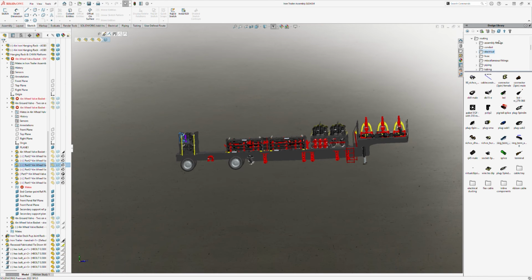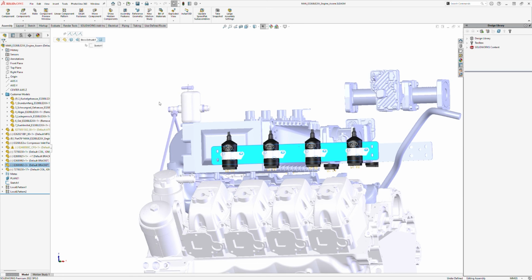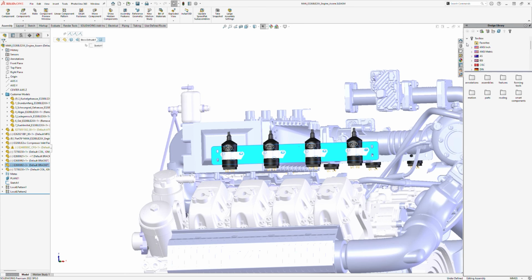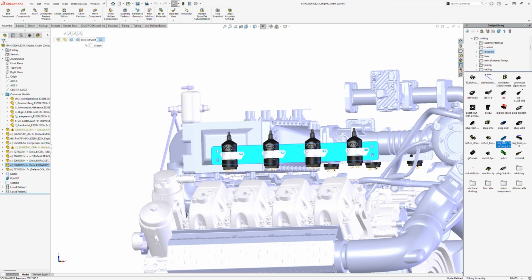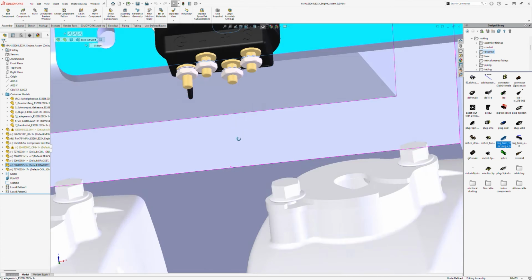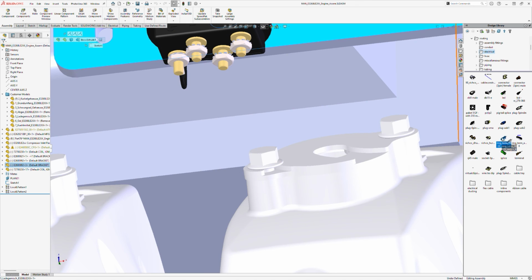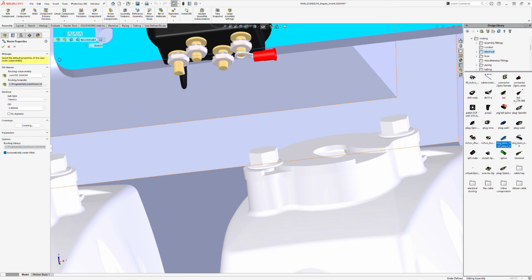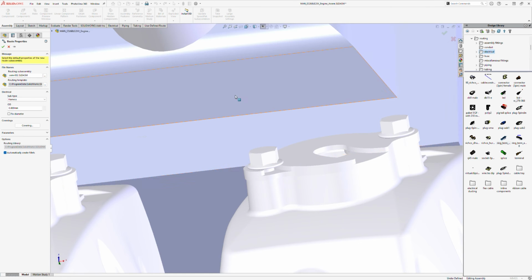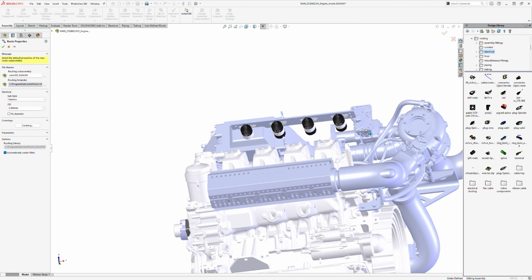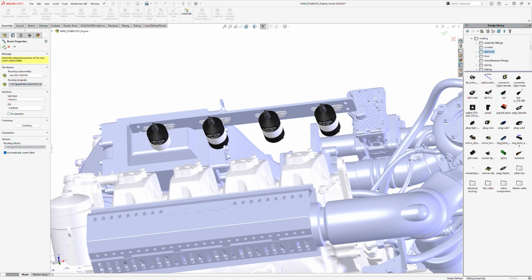Okay, so let's close this, and I'm going to open it up and try again. I've already loaded the same MAN engine 3268 file, and I'm going to begin another attempt at a route. So I'm going to design a wire harness here. So drag a ring terminal onto the stud. And I hope it comes through here, but just how sluggish this is, and you can see the mate reference got disturbed again, so the coil pack rail is just flipped again.